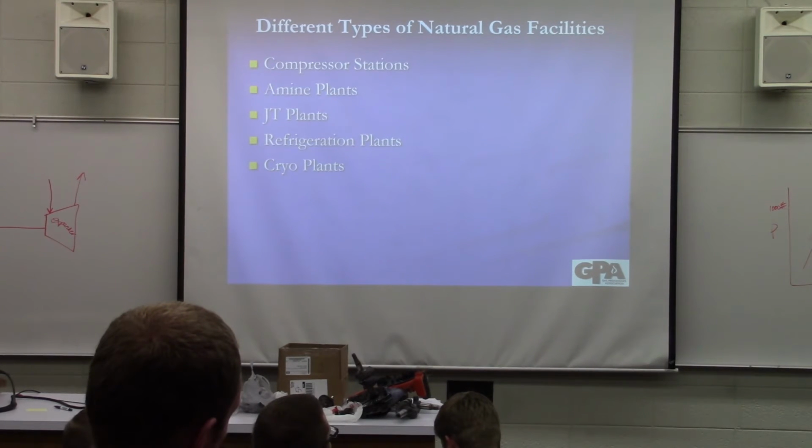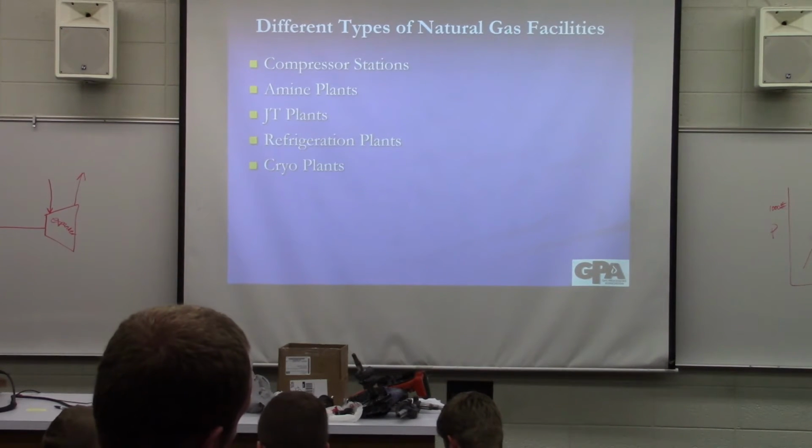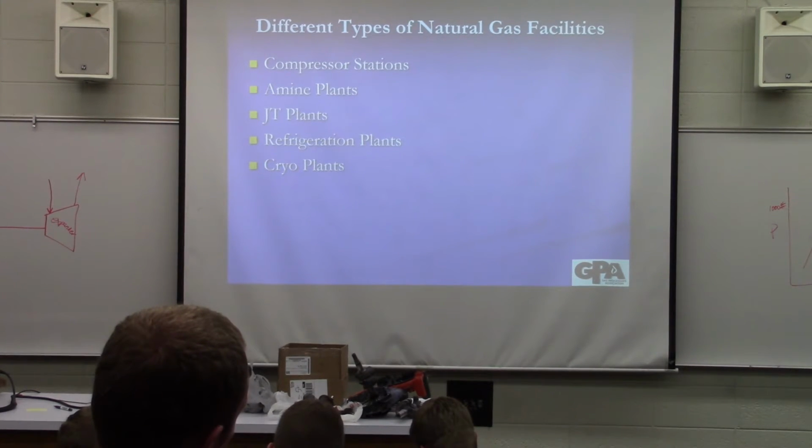I can say that again if you want. But essentially, if you ask me what's the cricondentherm temperature of this composition, the composition of gas that made up this phase envelope, it's going to be this temperature right here. Because what that means is, regardless of what the pressure is, if this is 15 degrees Fahrenheit, I can never form liquids if I'm above 15 degrees Fahrenheit.